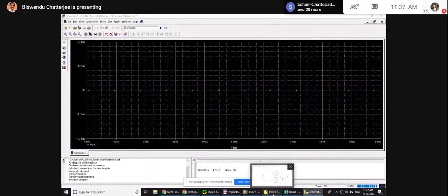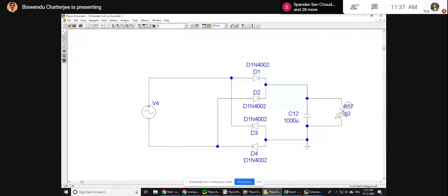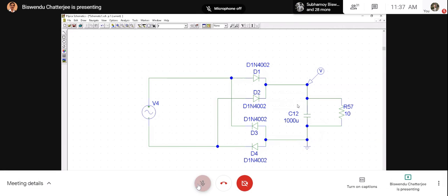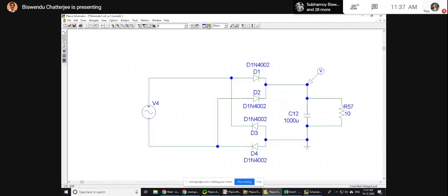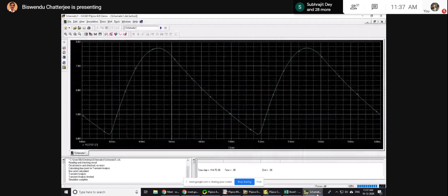Now with respect to reference, I want to see here. What do you expect here? First you tell me. It is the DC and filter capacitor. Some DC value I expect at the simplest. So let us simulate again. Simulation icon. This is the typical DC with ripple. Now see, it is starting at 40 millisecond and ending at 60 millisecond, as we have expected. Isn't it so?